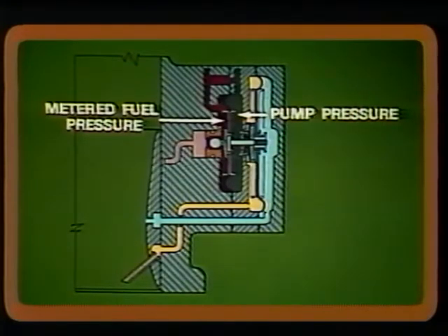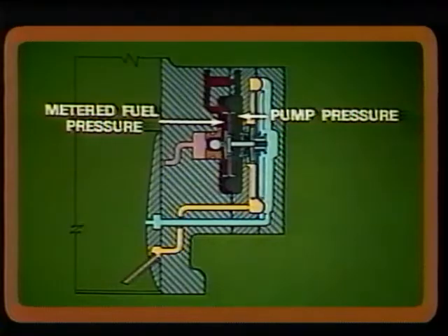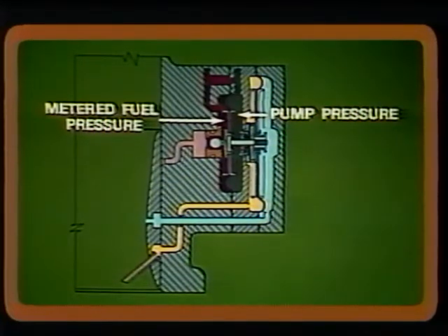The actual fuel metering force is comprised of engine pump fuel pressure acting on one side of the fuel diaphragm and metered fuel pressure on the opposite side. This arrangement helps balance out any fluctuation in the engine pump pressure, making this pressure less critical.